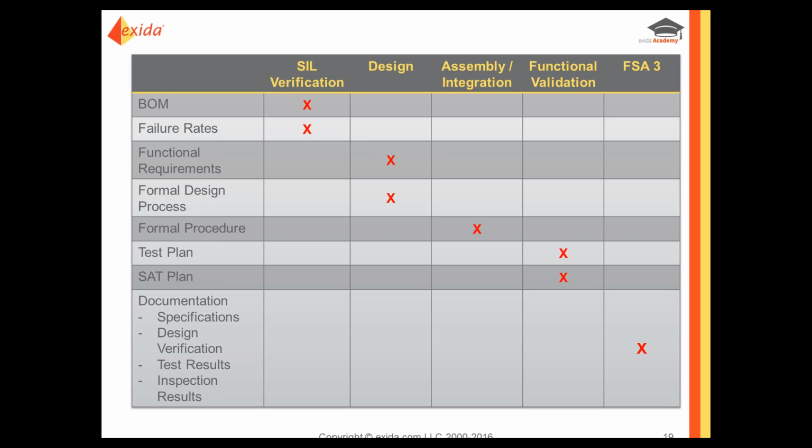Now, as a rule of thumb or starting point, if somebody is claiming dangerous detected failure rates for a valve or actuator without stipulating something like a partial valve stroke test, then it's invalid. I've seen some certificates claiming diagnostic coverage with no mention of any type of testing. So that's not really valid.